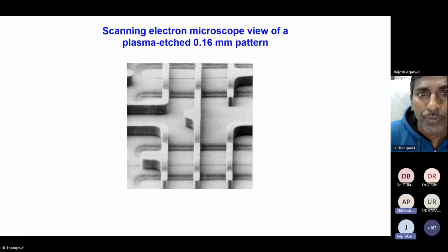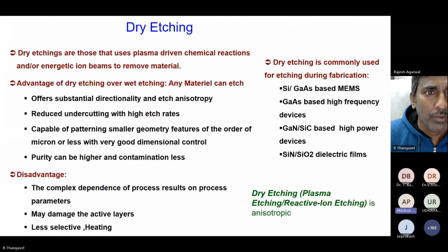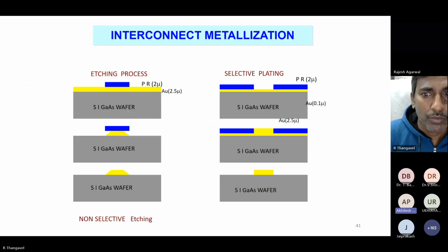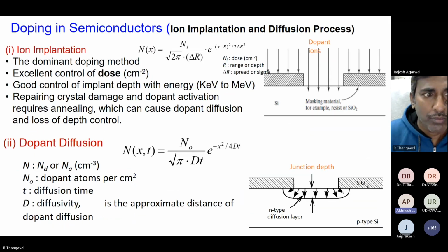Now, other doping techniques: gas source doping, where gases have to be collected, doping can be done. Solid source doping, where dopant diffuses from the doped solid film. In situ doping, where dopant is introduced in a controlled way while the silicon film is being deposited.